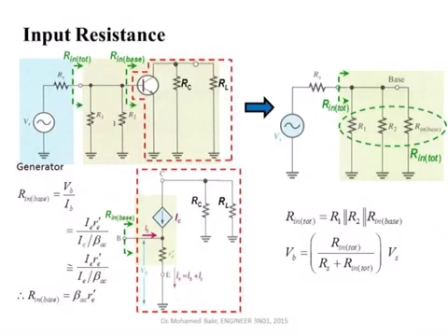I end up with beta AC in the numerator, and you can see that the input resistance is equal to beta AC multiplied by RE dash. To give you some feeling of the numbers here, beta AC can be 150, RE dash will be say 6 to 10 ohms. So this number will go between 900 ohms to 1500 ohms. So the input resistance seen into the base of the transistor for AC analysis, so everything here will be replaced by Thevenin equivalent, this one here I call R in base, and it is between 900 to 1500. Okay, so now we have this situation.